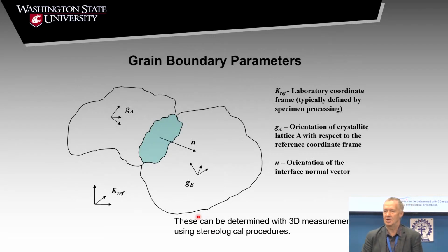So some basics on grain boundaries. We have 2 orientations related to a reference frame, right? So these are the orientations we talked about yesterday in defining texture. This is just orientation of grain A, orientation of grain B. There's a grain boundary plane between them, and any section of the grain boundary plane has a normal N. Usually our grain boundary planes aren't planar, right?